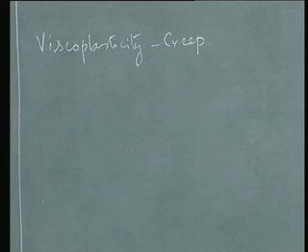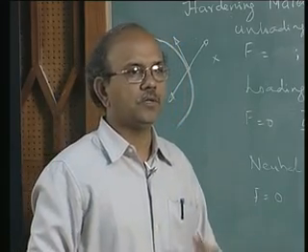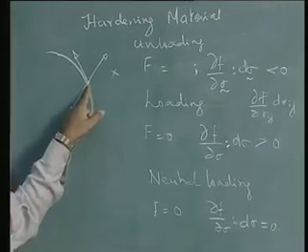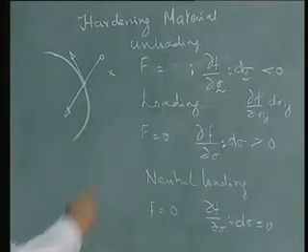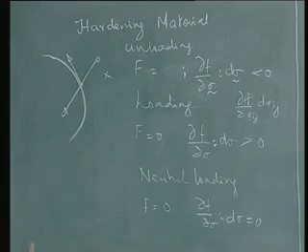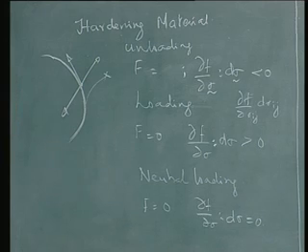And when you say creep, you immediately think of so many other issues like relaxation, stress relaxations, and so on. So in the rate independent case, the point may lie in the yield surface, but for a rate dependent case, points can lie outside the yield surface, and then with time they will relax back and fall at the yield surface.